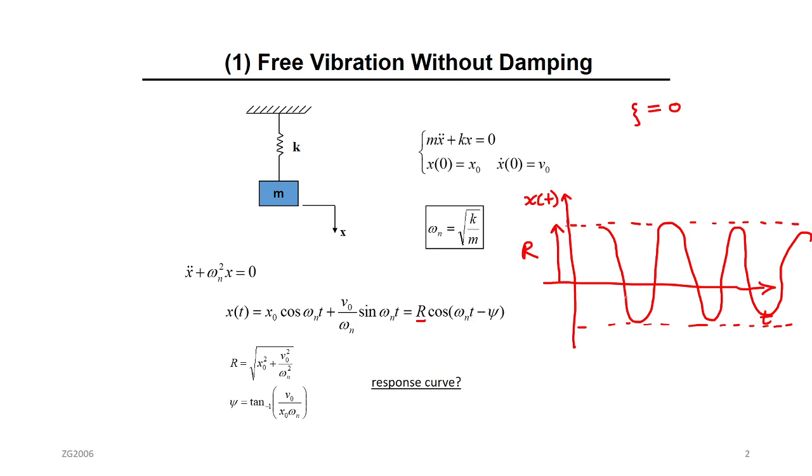Here we're going to focus on how to draw the transient response only. The solution, you can check that for proof. But it's going to be always the same. So if you remember how to derive R, it will be the same. What about this distance from here to here? We call this the phase shift. You see? It's leading or lagging? It's lagging. How much? Psi. This is psi, starting from this point. This is the phase shift. And this is the amplitude.